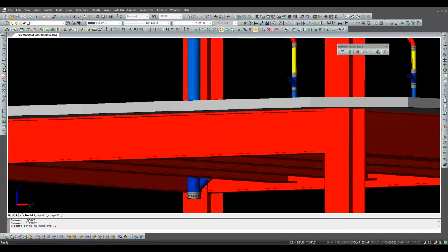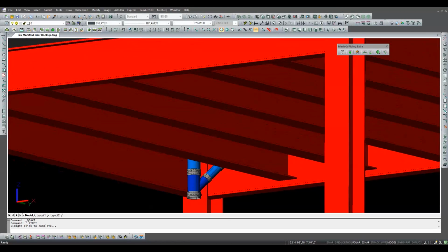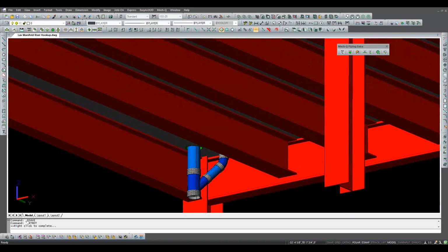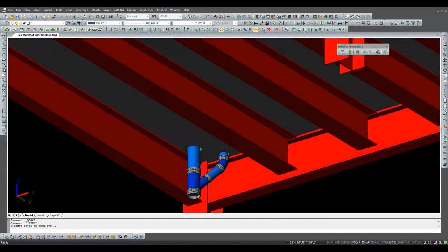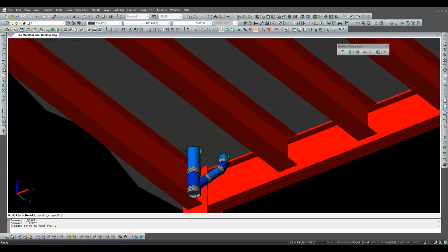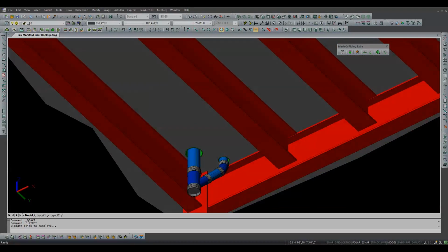Once again, the slide routine has used the power of 3D CAD to allow us to make this connection without calculations or troublesome 3D construction lines. But most importantly, it eliminated the need for expensive field cutting and fitting of the connecting pipe.